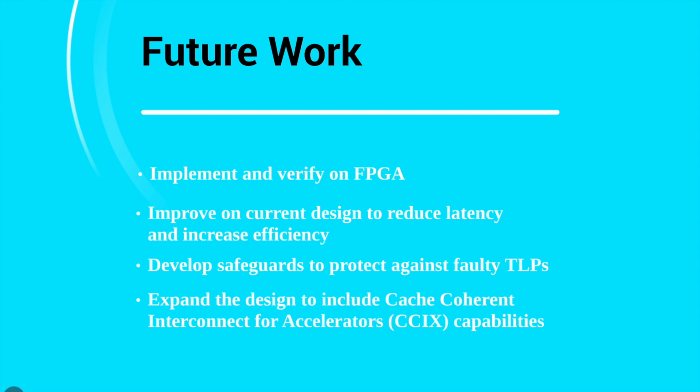For future work, we want to implement and verify on an FPGA. We want to also improve on the current design to reduce latency and increase efficiency in any way that we can. We would also want to develop safeguards to protect against faulty TLPs, as it is difficult to detect these and to handle them. We'd also want to expand the design to include CXL, the cache coherency interconnect for accelerators.